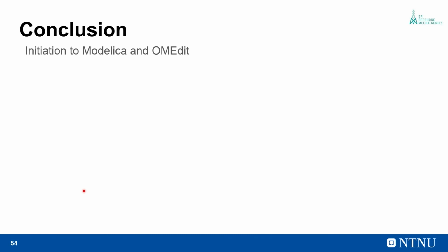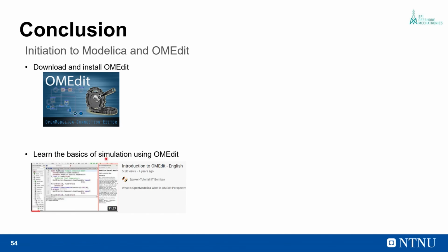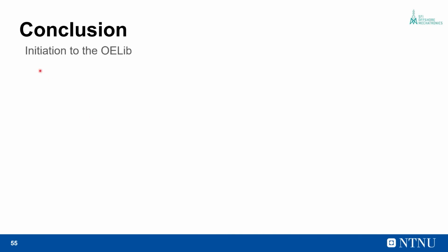I often get asked how one begins with Modelica and OM-Edit. So the best way is to first download and install OM-Edit on your system. Then learn the basics of simulation using OM-Edit, using the spoken tutorials from IIT Bombay, for example. Explore the Modelica language, and you can use resources like the website Modelica by Example by Dr. Michael Tiller, who is a Modelica expert. And once you're comfortable with the Modelica language, you can get initiated into the Ocean Engineering Library.